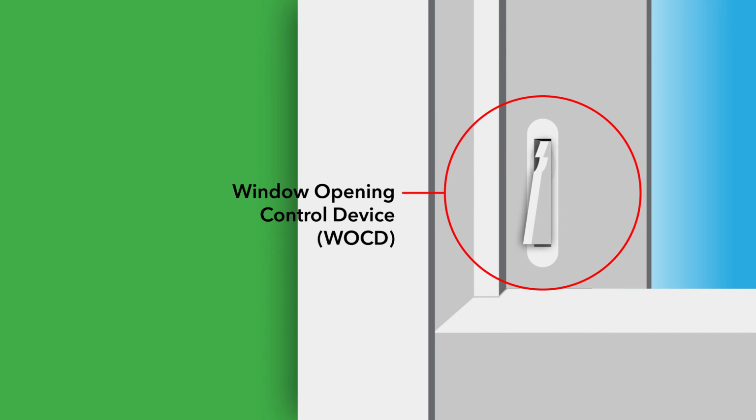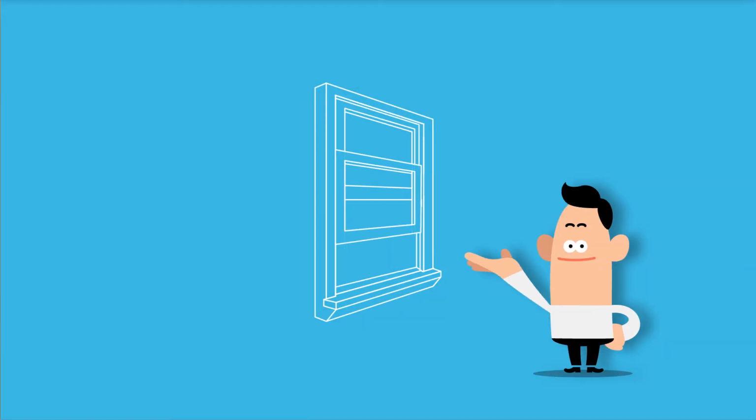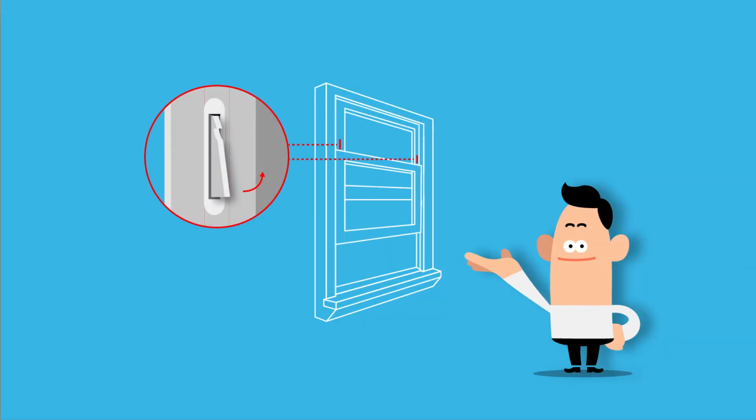They are found on the vertical sash stiles and are always activated for fall prevention. Some windows also come standard with night latches, which when activated can allow ventilation without a large opening. These small pieces of vinyl are located on the top sash stile and pop out to position sash for optimum ventilation. There are lots of moving parts to windows that help improve their functionality.